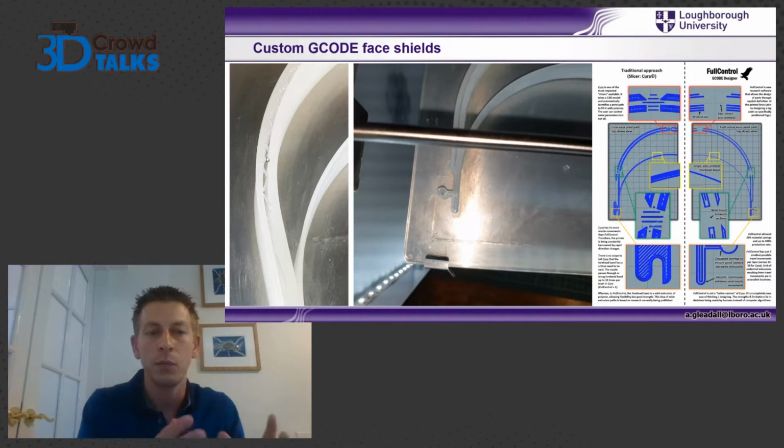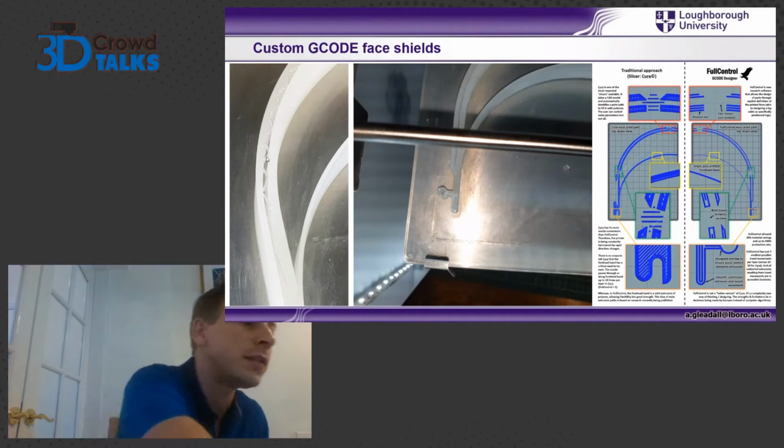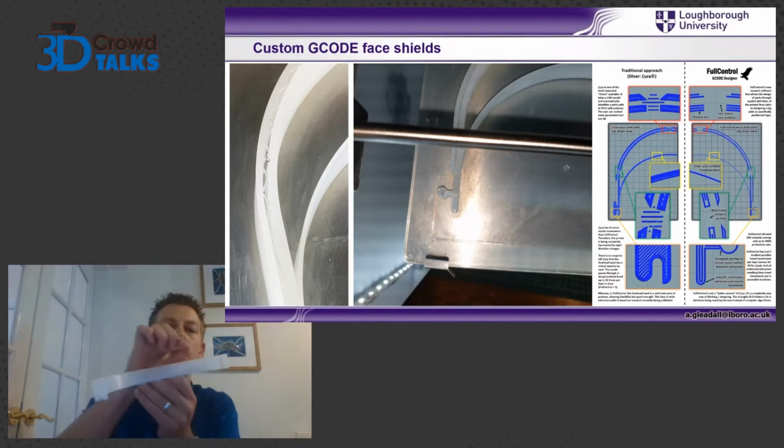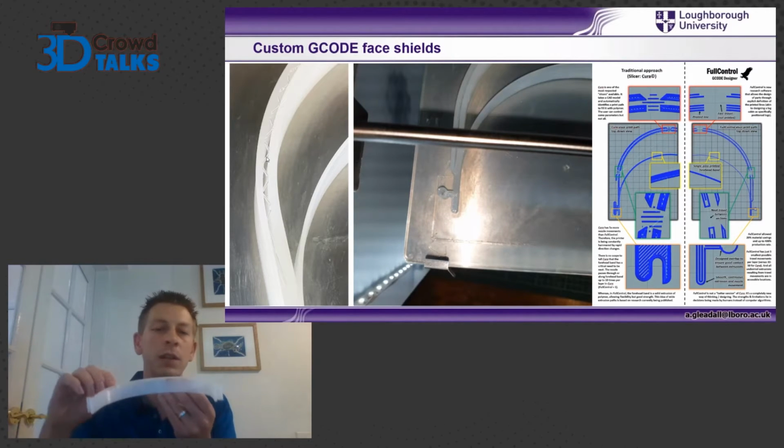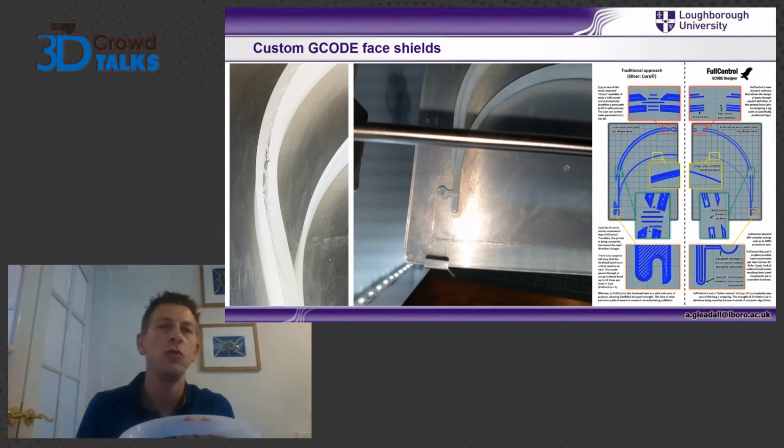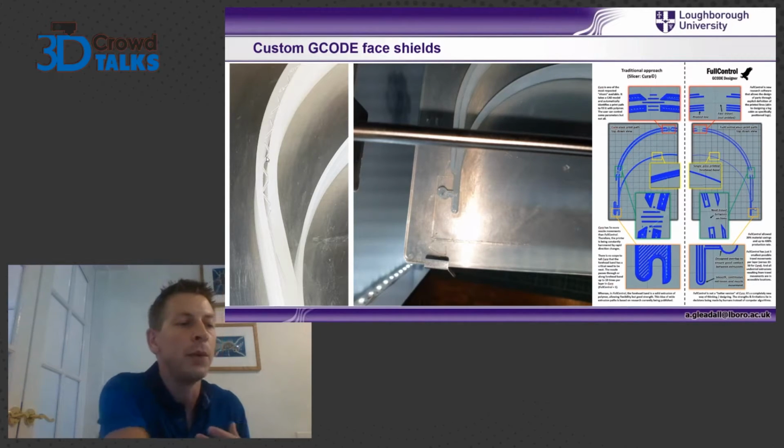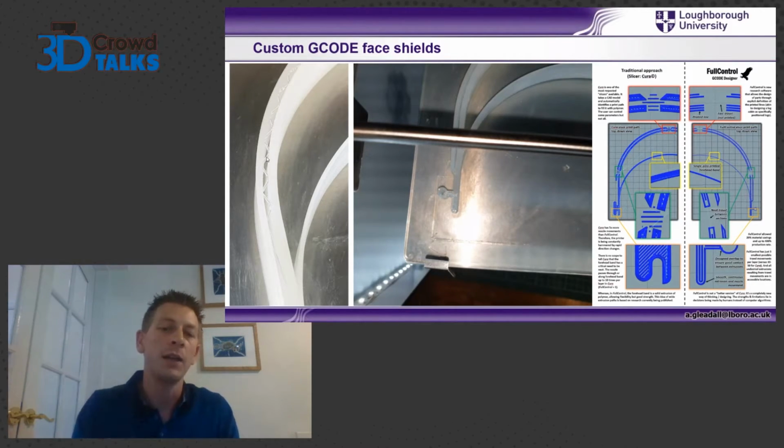And that's part of it. And also when we had the stack of these, the layer in between was fully designed. You know, we optimized the extrusion rate, reduced the number of lines, so defined a whole new toolpath effectively for that layer in between. What that meant was they could just be separated by hand and then a quick sand, and they were all perfect quality. So we could get really, really high throughput.